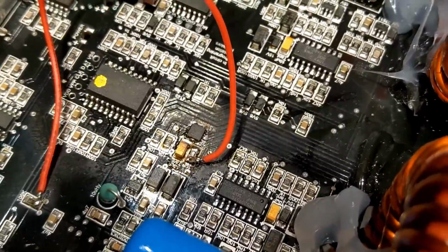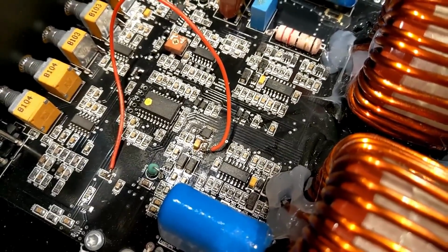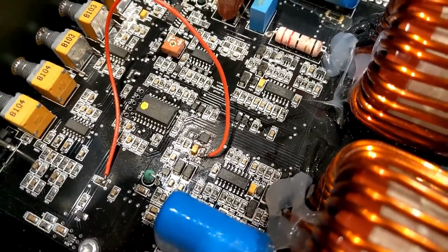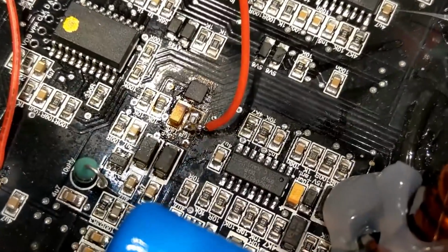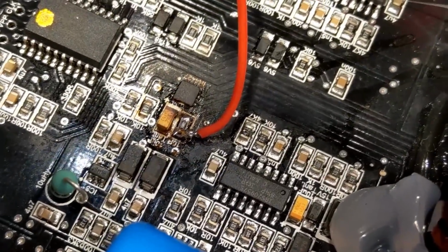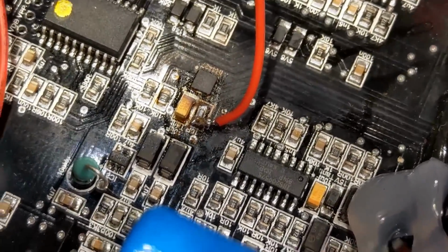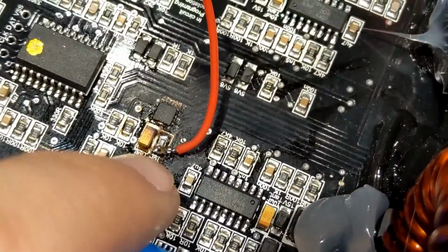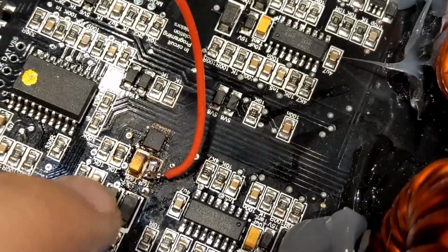And I did have a schematic on hand, which was useful, and I confirmed that that's supposed to be tied to battery voltage, and it's not supposed to move around. It's supposed to literally be battery voltage at that terminal there, VCC. So it turns out that probably somewhere on the board, there's a blown trace that is meant to connect this side of the 10 ohm resistor, which is for this drive IC, to the battery voltage.